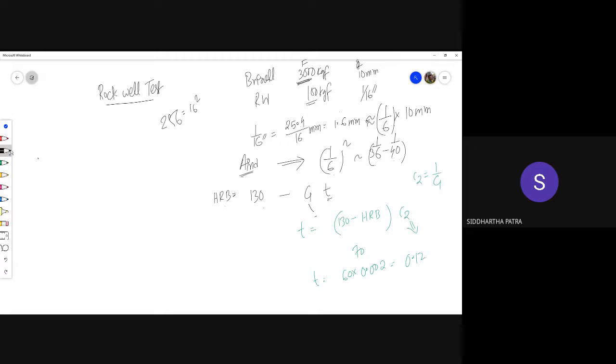So next thing is the purpose of a minor load. One thing to notice is that the indenter in the Rockwell test is substantially smaller than that in the Brinell test, and there are some advantages to that. You can do multiple indentations on a given area, but there are certain problems associated with that.